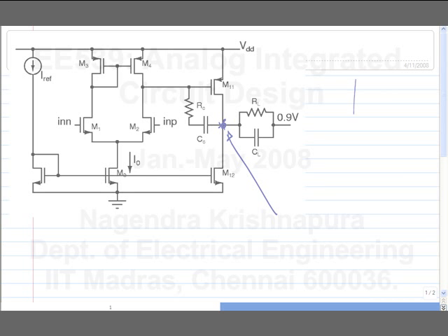If you use an op-amp in feedback, what is the quiescent output voltage here? Huh? So it is basically the quiescent voltage at this point. Of course, it's logical to choose 0.9 volts in a 1.8 volt supply to be the quiescent point, but it doesn't have to be.